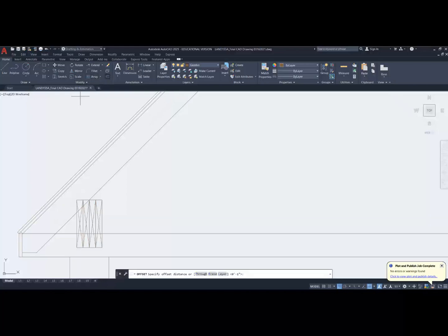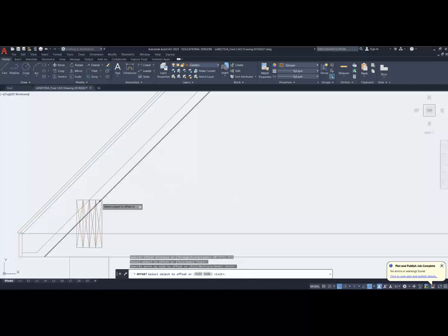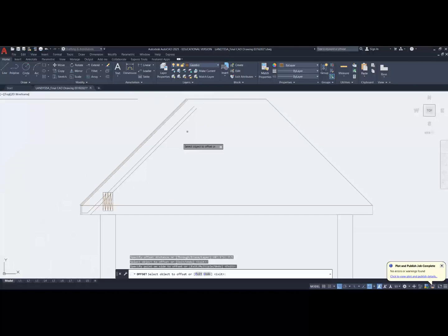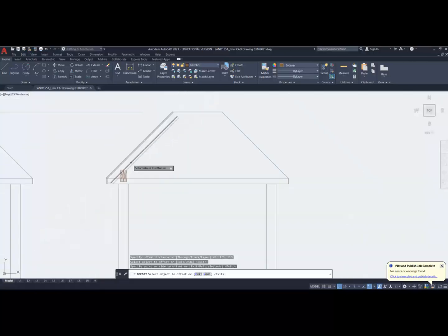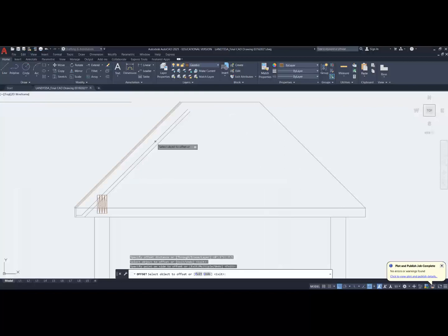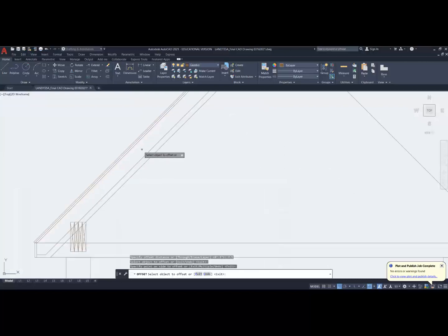Let's see how that one sits. Offset, 7.5. It's always from the sheathing line down. See how that nicely fills that? And I may want to use that just because it's obviously stronger, especially along the long leg. Although this roof isn't that big, realistically speaking, a 2x8 or 2x6 can easily support that. And next year we're going to look at tables and charts that will help us identify exactly what size. But a 2x8 would work as well because it sits nicely on there.